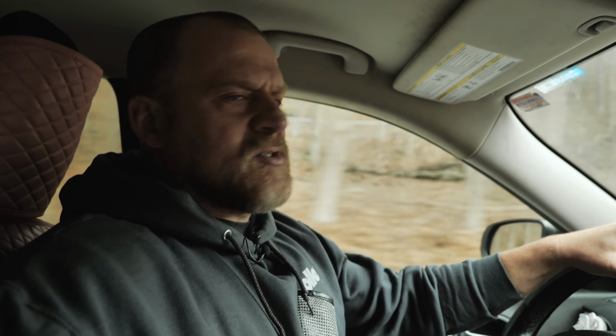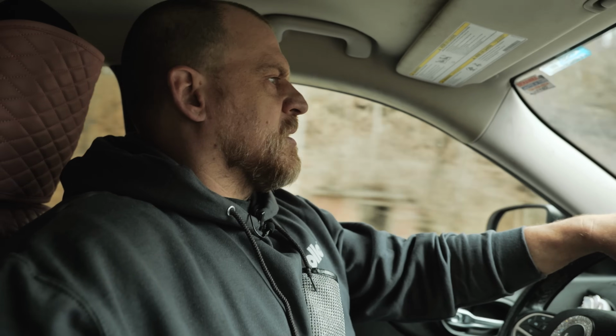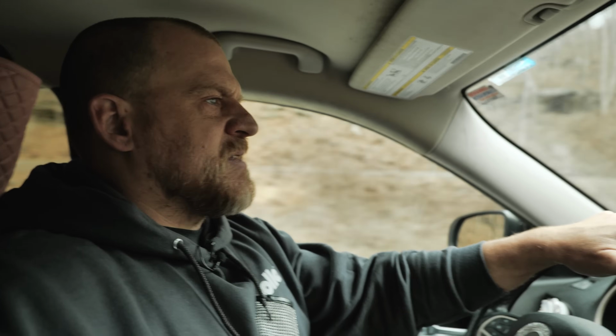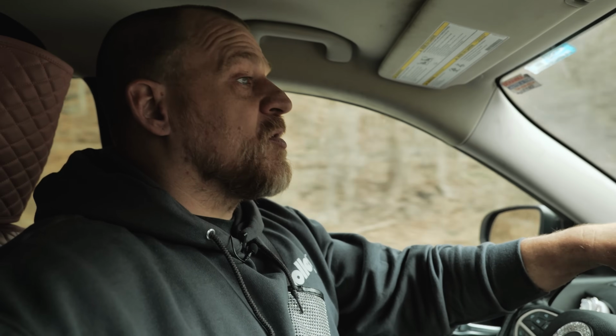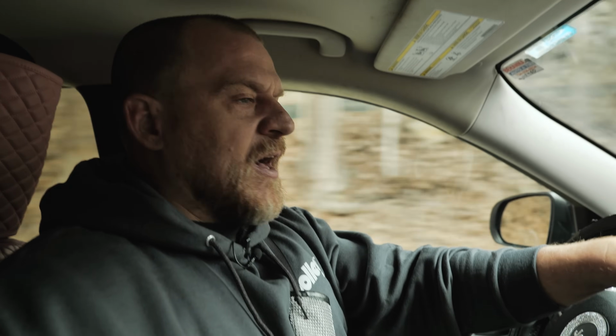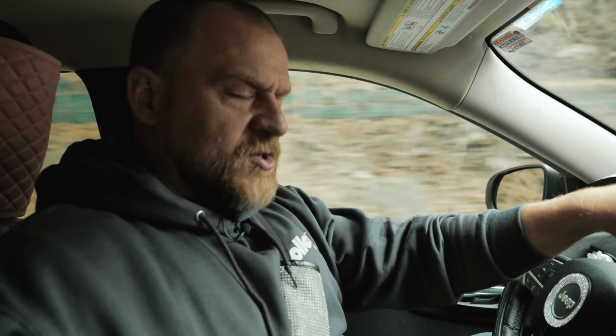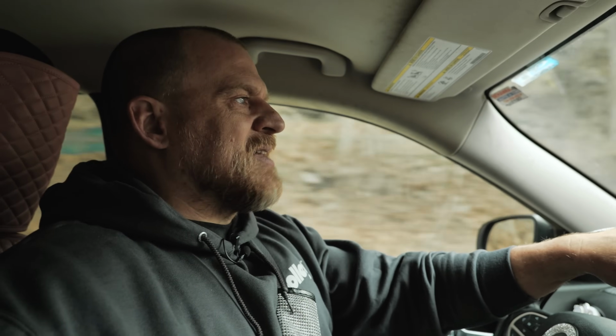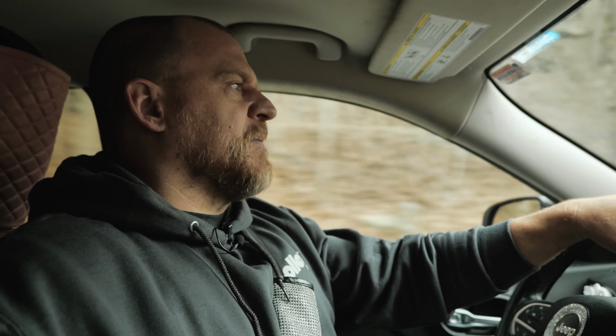I have some case studies on that right here on YouTube. We'll link a couple of those where we had intake gaskets that were more pronounced when the engine was cold, almost went away completely with the engine hot. So you can have that. That's why I mentioned engine temperature. I didn't look at temperature, and I should have on the freeze frame.